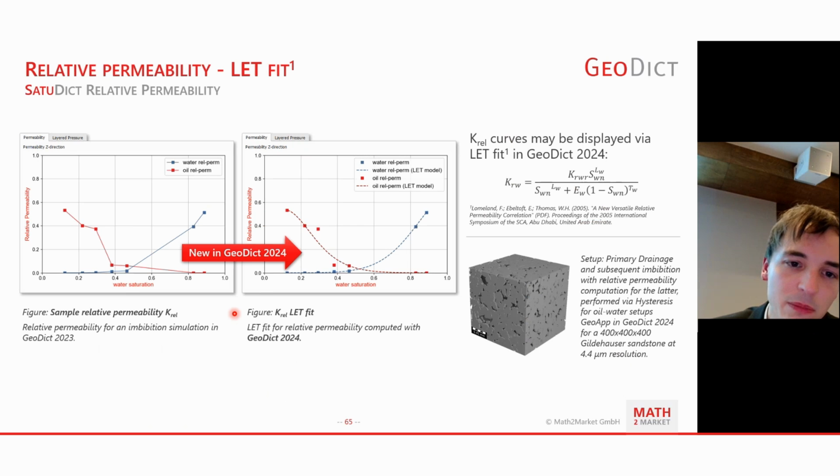I think for the sake of time, I will only explain very briefly that the LET fit not only smoothens your curve out, but it also takes the irreducible water and oil saturation into account for that fit. So it is not only a mathematical model that fits the curves somehow, but it is a fit that was designed specifically for fitting relative permeability curves.